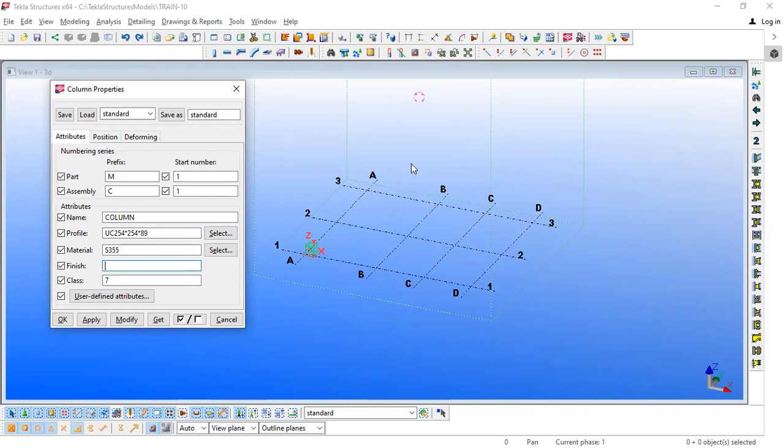Whenever you are generating a drawing and you find that the paint note is missed in certain columns, there will be a rework of finding those items and then applying those finish codes. So that's why it has to be applied at the very beginning of the model.